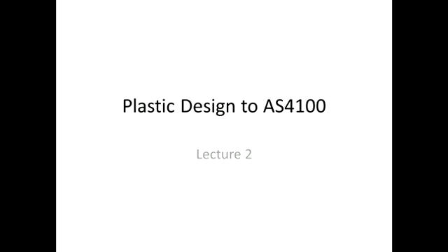If I said to you I had a shape factor of 1.5 for one cross section and a shape factor of 1.1 for the other cross section, which of these cross sections did we say might benefit more from plastic design? Yeah, so the one with the larger value of shape factor.